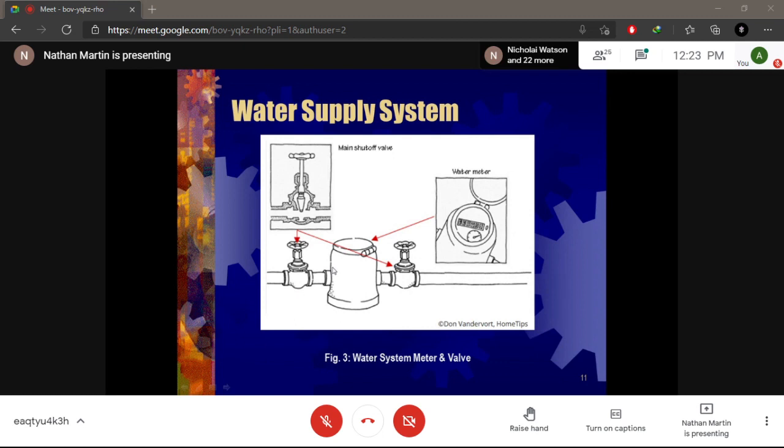We have galvanized union and we have PVC union, right? Anything you can get in galvanized, you can get replicated in PVC type material. The galvanized pipe has advantages and disadvantages. Same thing with PVC. The main disadvantage why we chose a couple years ago to move away from galvanized pipes to PVC pipes is rust, right?